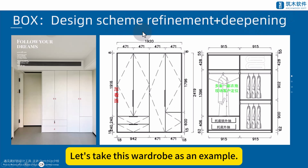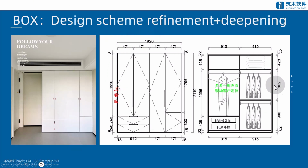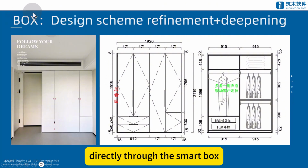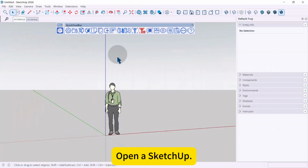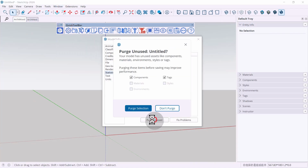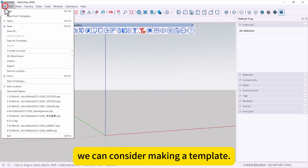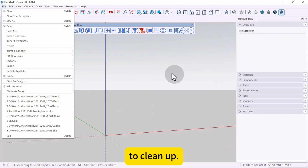Let's take this wardrobe as an example. This wardrobe is actually the case we talked about in the previous video. Now, without using CAD drawings, directly through the smart box, we create the model step by step. Open SketchUp. Delete unnecessary objects, then clean up the model of unused items. Of course, if doing this every time seems troublesome, we can consider making a template, so we don't need to clean up every time.